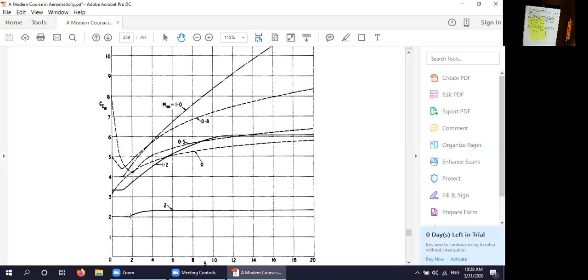And then it goes up a little bit from there. It actually waits a while and then it goes up. But the difference between this curve and this curve is the difference between about 2.3 at large time versus 2 at short times. Here it would be 1 versus maybe 1.05 or something like that. As the Mach number gets very high, this result just becomes a horizontal line. That is, the lift does not change as a function of time at very high Mach number, according to this model. Does that help?